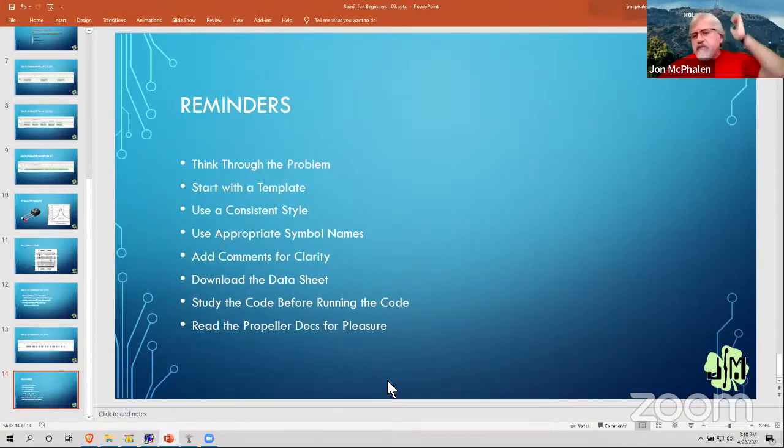For those of you with a good visual memory, that debug panel that was on the front was showing that you can have up to 18 channels with S-Bus. There are 16 analog and two that are digital, but that's coming in on one pin. And it's updating every 7 to 10 milliseconds. So that's plenty fast enough.